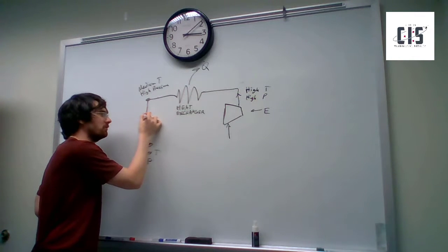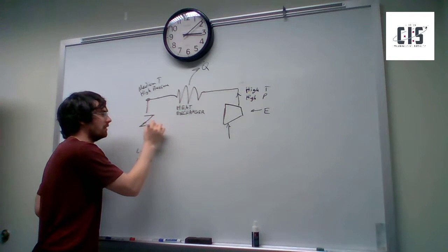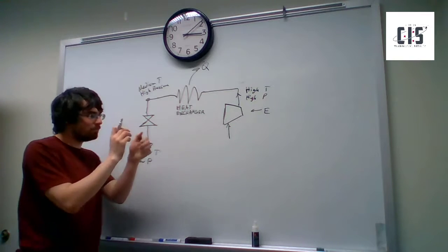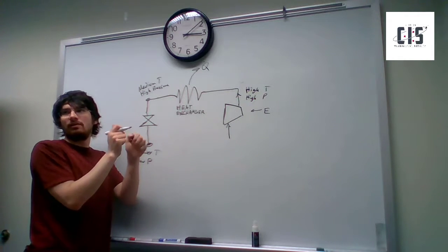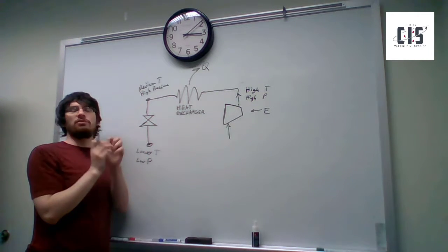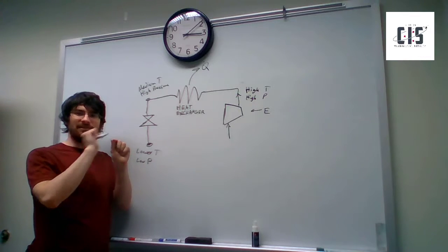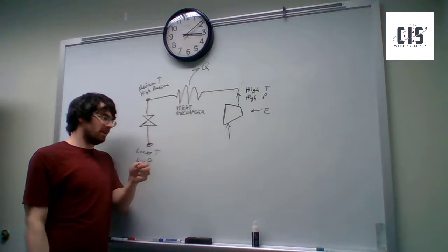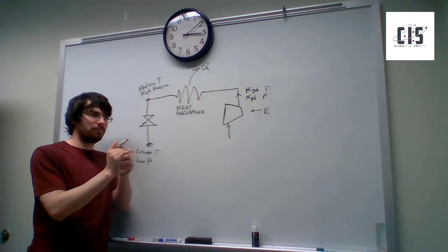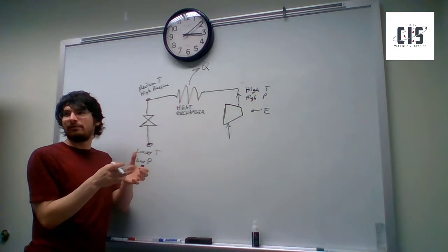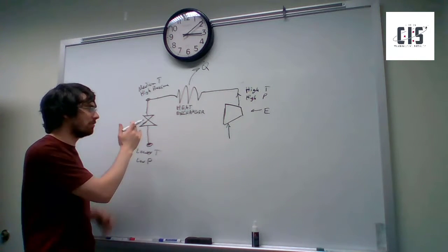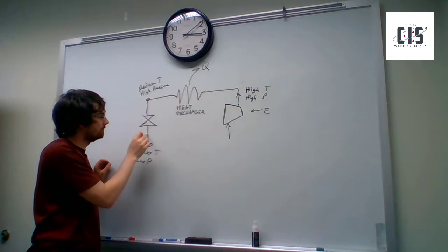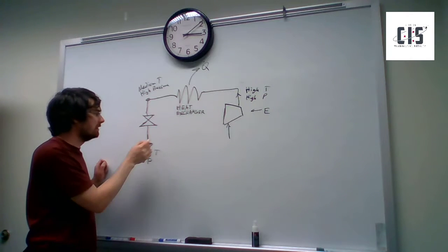The simplest one is just to use what's called a throttle valve. It's basically just a valve that's slightly cracked, so it has a restriction in it, and it's very difficult for the gas to get through it. Because of that, the gas has to speed up to the speed of sound in that fluid, and the pressure is going to drop significantly across this. I guess it's kind of like a reverse compressor in a jet engine. A little bit like that.